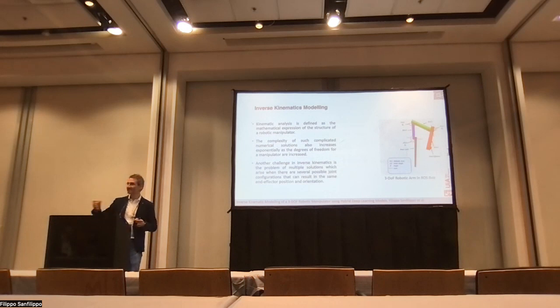They cannot coordinate their arms. So basically, it's the same idea. We use a simulator to randomly generate poses for our robotic arm, and then we build our database. And based on this, we can then apply machine learning algorithms to infer or to learn the inverse kinematics of the model.